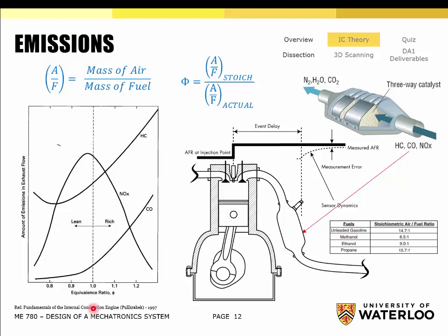So why is the equivalence ratio important? Just because this graph here is shown on a graph of equivalence ratio. An equivalence ratio of 1.0 means that it's fully oxidized and perfectly stoichiometric. So you can see here how the emissions for an internal combustion engine would vary with equivalence ratio. When we're operating at stoichiometric, which is where the engine is targeting during most of operating a vehicle, it's because the carbon dioxide or carbon monoxide emissions are low when you do that.